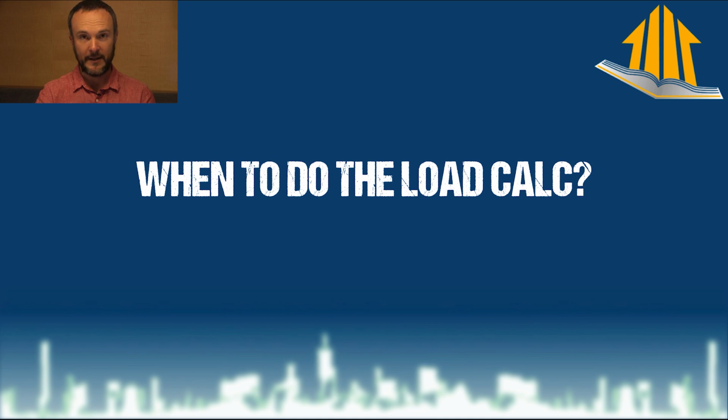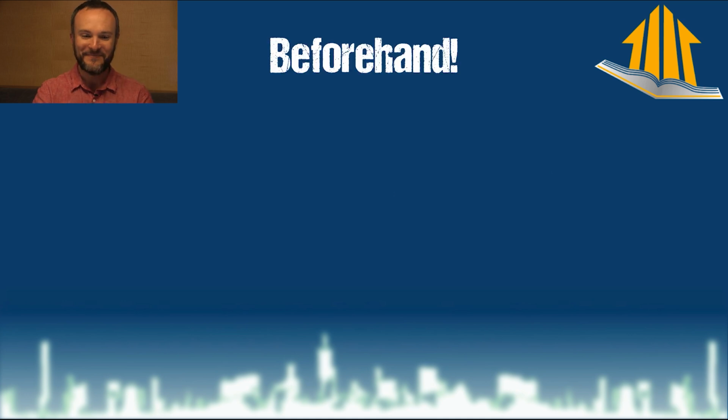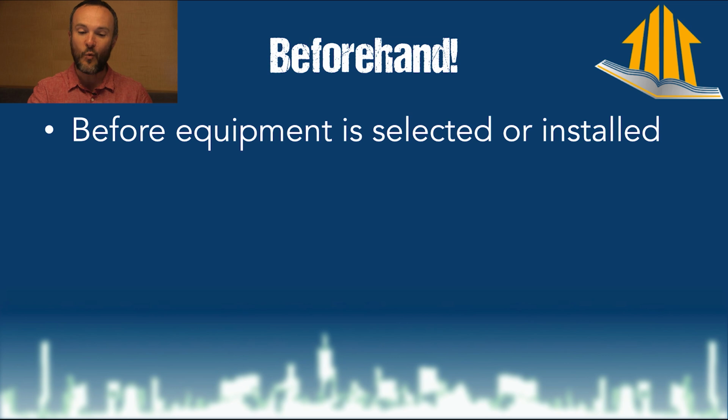When do you want to do this? Always beforehand. Really important, because once you select the equipment, you're going to be doing the duct design. Once the duct design is done, you can't go back and redo the equipment. So you need to make sure that this is the beginning of the process.